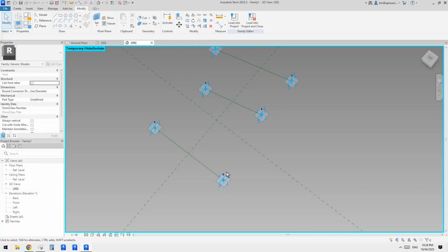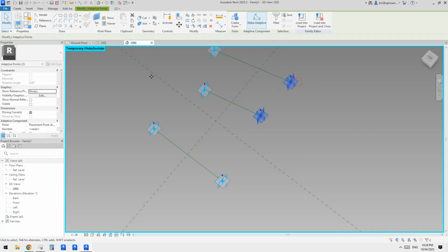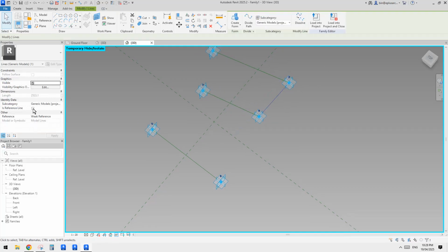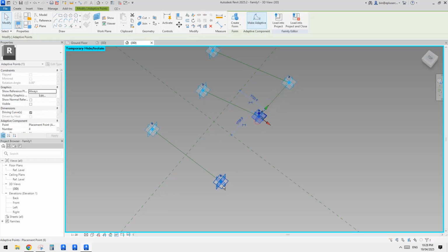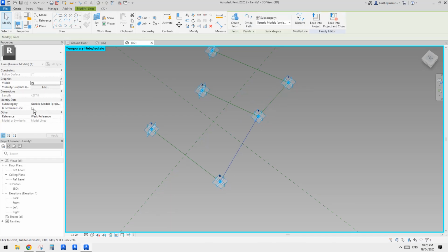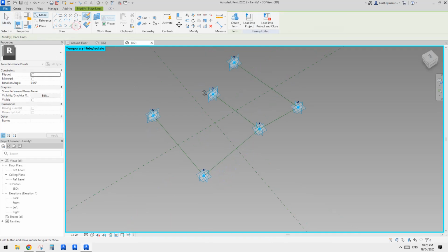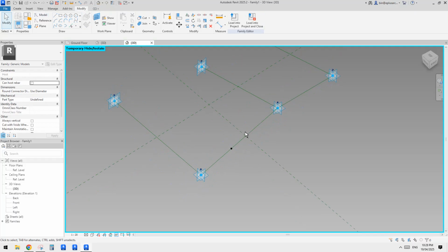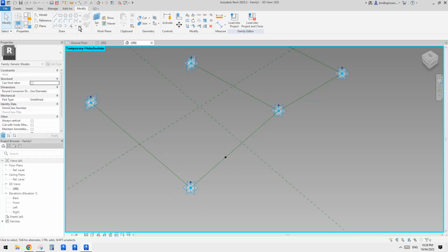Okay, we don't have lines between, yeah, we can just create, right? Spline through points again, just make it a reference line, another one, and then we can just place a point, use draw on face, place onto this line, and then we'll be fine. And also because we have 2 lines as path, we only need one profile.